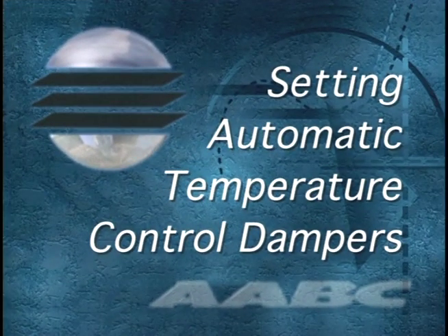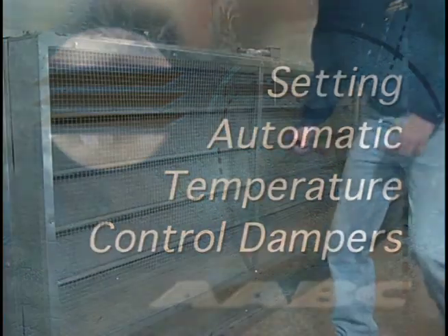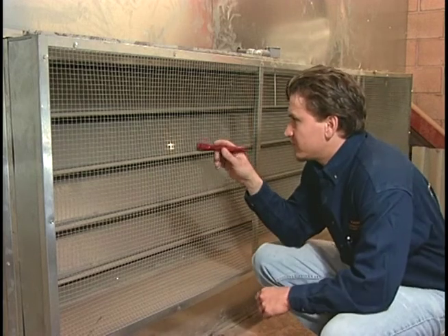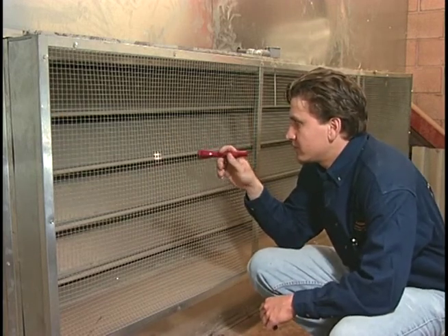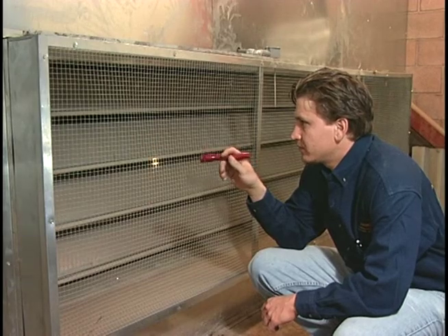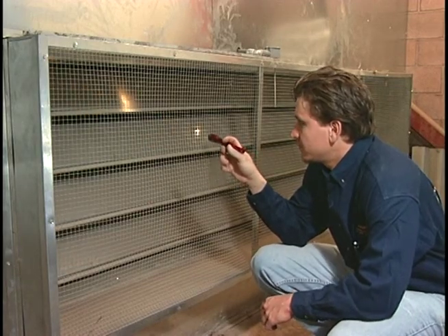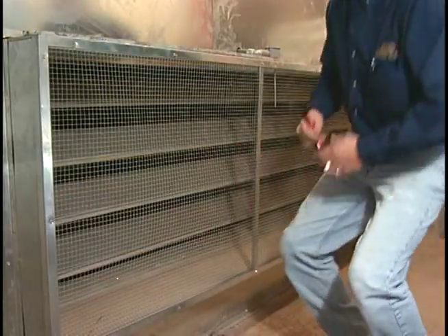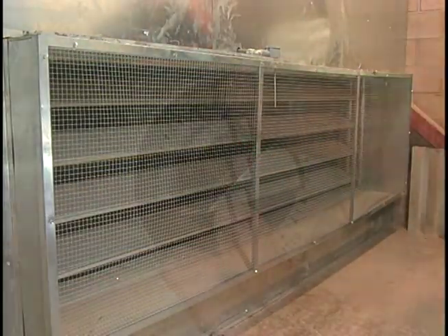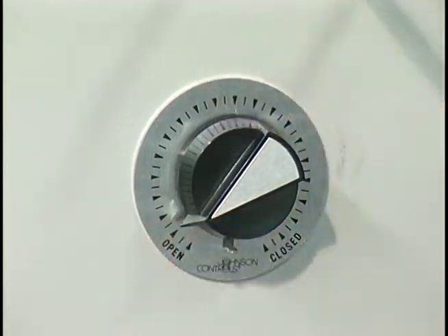Setting automatic temperature-controlled dampers. Proper damper position during TAB work is critical. The technician needs to be familiar with the sequence of operation of all the dampers in the system. If large dampers are incorrectly closed on startup or while the fan is running, serious damage could be done to the ductwork, filters, plenums, and other system components. When practical, the technician will work with the control specialist to ensure that the automatic temperature control dampers are positioned properly for balancing.